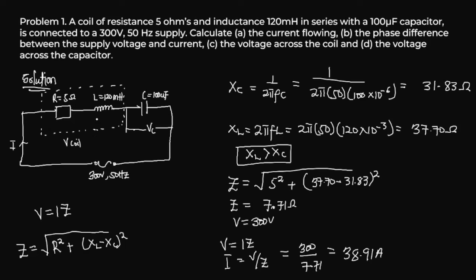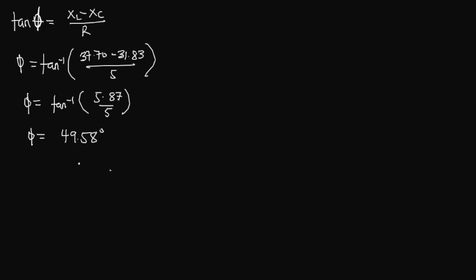So we need to find the overall resistance to the flow of current in that particular coil. Then we can find the voltage across it. Because we already have the current flowing through, we need to find the overall resistance. When we combine a resistor and an inductor, we need to find the overall resistance before we can go ahead and find our voltage.